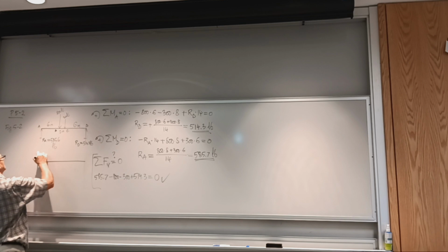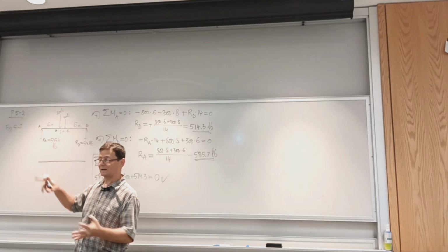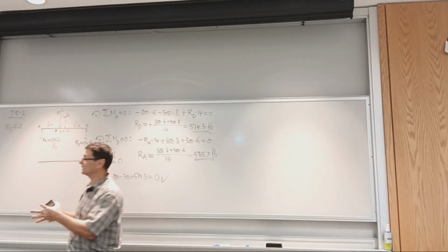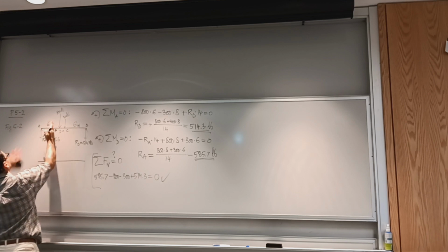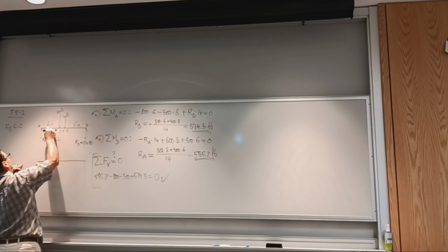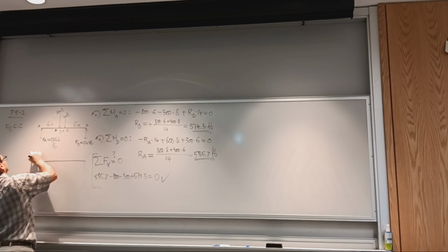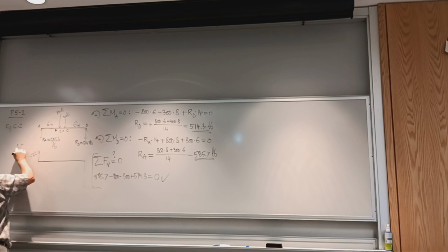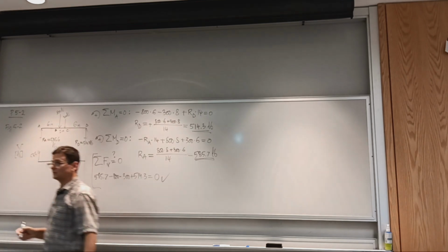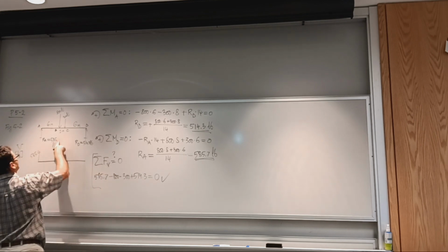Is that right? So again, an external force going up raises the diagram. Internal shear is positive on the diagram for the left-hand section. So if I do a section and I look at this piece at this end of the beam, a shear that's down is actually showing positive on the diagram. The external force is causing the diagram to jump. And I start with 585.7, and we usually say V and put units here, pounds, rather than carrying units on the diagram.